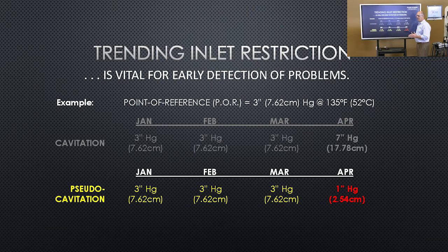If I'm aware that a hydraulic pump is cavitating, I cannot say, well, let's just run it to the end of the shift. Any problem with the system is a pending catastrophic failure. It can certainly result in that, and it's going to be systemic. So my first question is always, if I am aware that there's a problem, but I want to get to the end of the shift, if during that period of time the unit fails, could the operator lose control of the machine? Could it cause an accident?